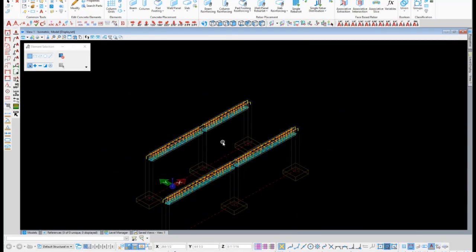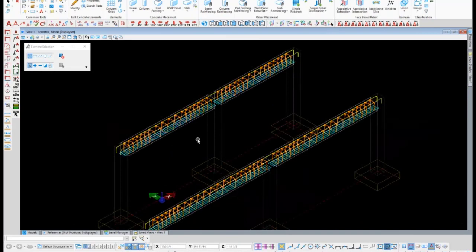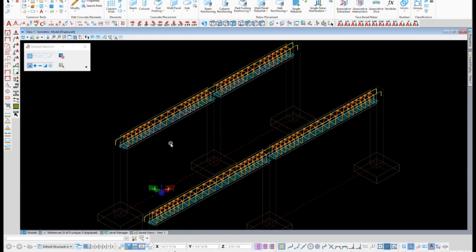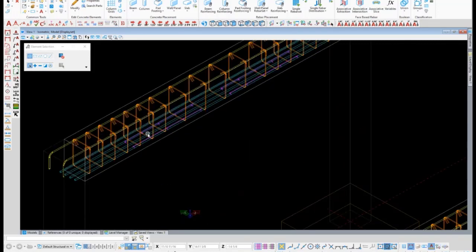Truly it is that simple. Whenever you start working with beam macros, spend a little bit of time up front, set your macros, get them right, get them proper, and then as you're working the project, you can simply click through your beams, knowing it's a right end, left end, or a continuous type support. You can make quick adjustments, again, by adding in additional macros, taking them away, putting them in the position that you would want to see them from the beam's perspective, and rolling with it.